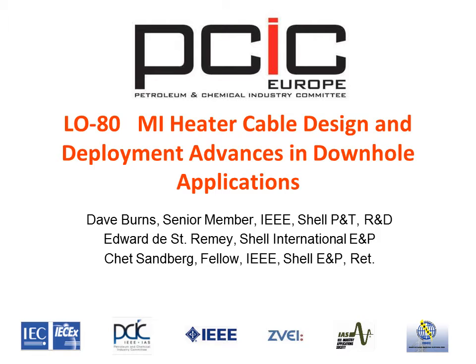I'm the co-author of a paper entitled MI Cable Heater Design and Deployment Advances in Downhole Applications. What we're talking about here is a long heater that operates at a high temperature in a long horizontal well in Alberta that is used for either viscosity reduction or in situ upgrading process, converting 10 API oil into 40 API oil.